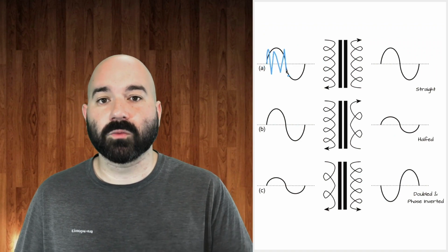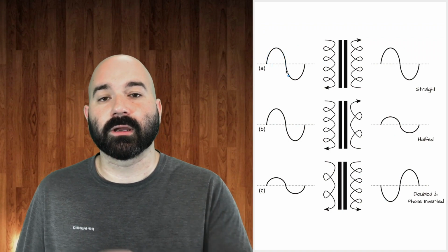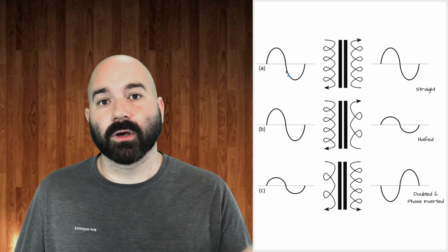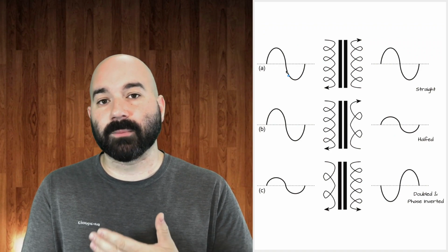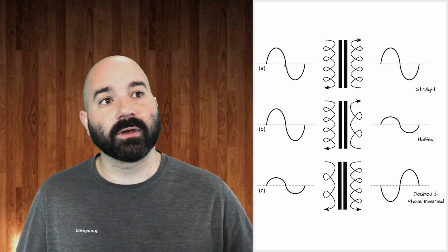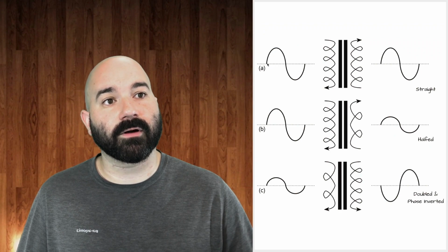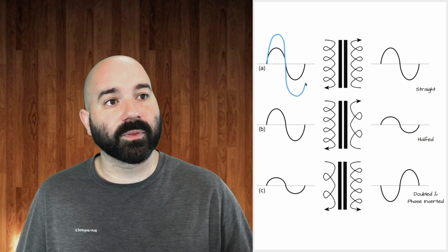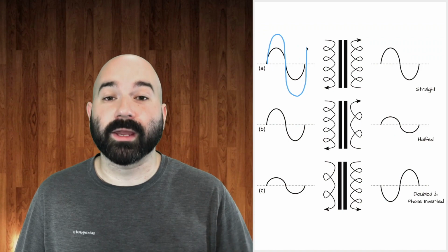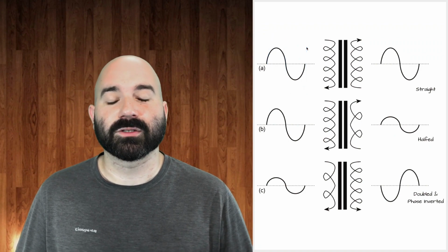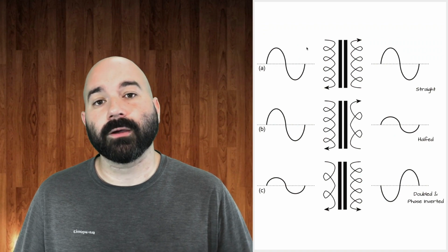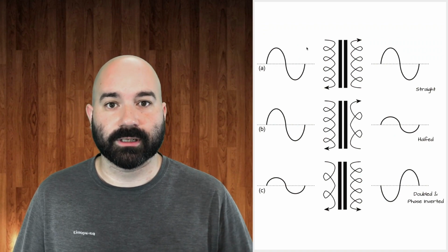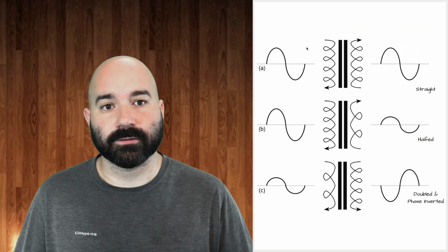So we have a one-to-one correlation of frequency from sound pressure to electricity. And how far the diaphragm moves, based on the amount of energy from the sound pressure wave, directly correlates to how far from equilibrium the wave will move in electricity. So again, we have a one-to-one representation of sound via electricity in an AC current.